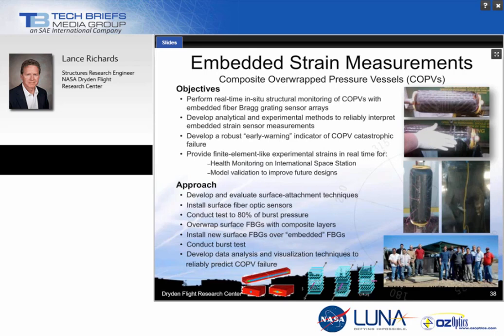But the approach that we took, how are we going to discern the strain measurement and understand what it really means in terms of its physical significance? So what we did was we took these bottles through a collaboration with White Sands Test Facility, being sponsored by the NASA's NDE working group, and we installed the fibers. We had to develop some attachment techniques because they're somewhat challenging surface roughness.